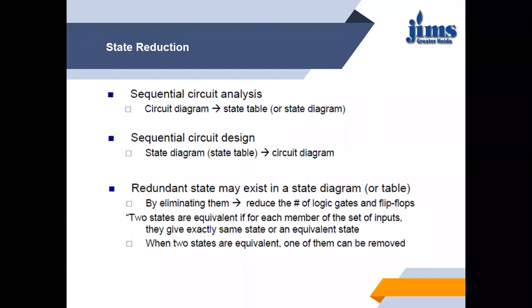There may be some redundant states existing in the state diagram or the state table. By eliminating the redundant states, we reduce the number of logic gates and the flip-flops, because the number of states is responsible for the number of flip-flops and hence the number of gates. So with the elimination of the redundant states, we are reducing the cost of our final design and hence the complexity of the design.